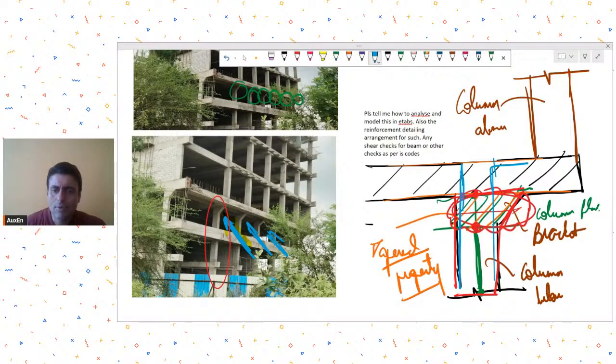After providing certain development length, you can just curtail it. And then this additional bracket reinforcement, after providing the necessary development length, you can have it like this. Additionally, for shear transfer, you may create some bracket reinforcements over here, stirrups, which will take the shear forces. So all the checks will be as per your normal brackets, normal cantilevers that you do.